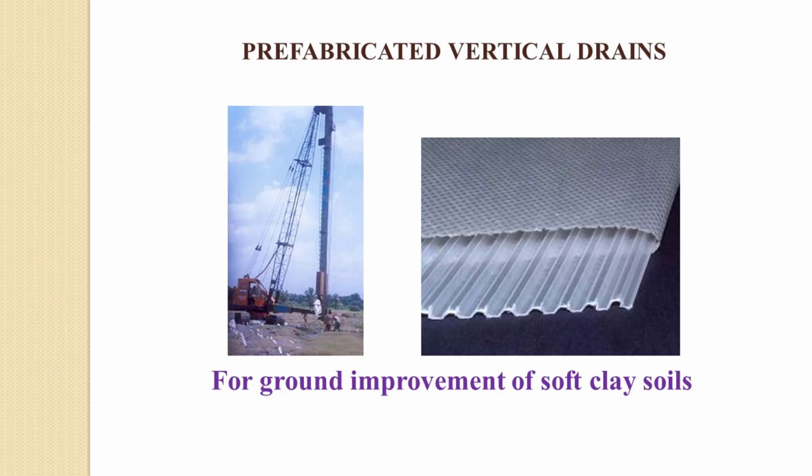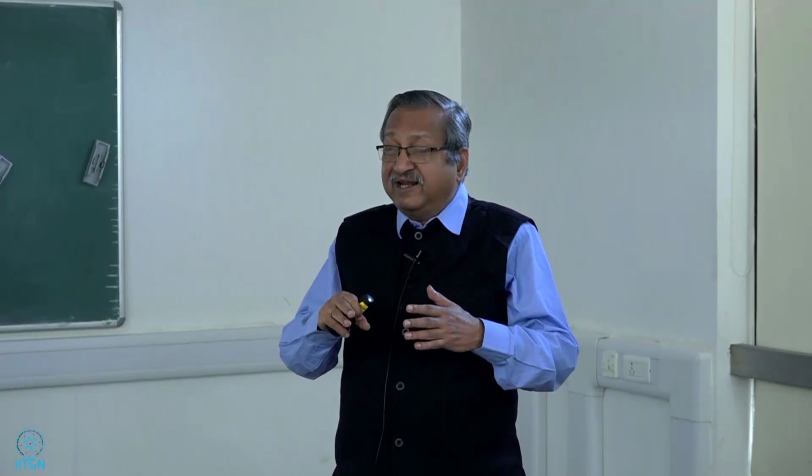But what is involved in the consolidation process? The moment you do the consolidation test, the moment you put a load, first the load is taken by the water which is in the spaces, and slowly the water, if you have a drainage arrangement, drains out. In the process the load is transferred to the particles, the clay particles, and they come together, they get compressed, and this is the whole process. Now what we have to do? We have to put a load, we have to provide a drainage path. If we do both that, probably we will be able to accelerate the entire consolidation process.